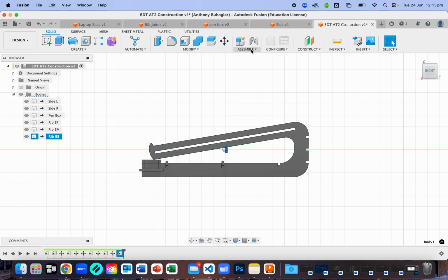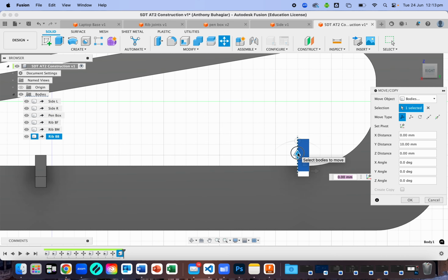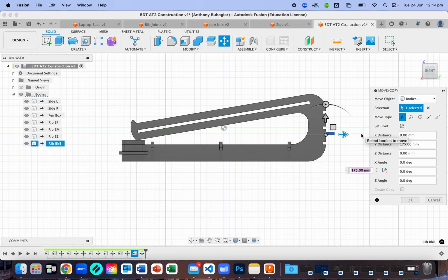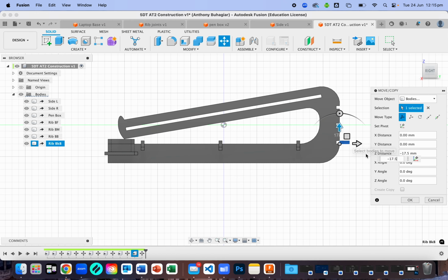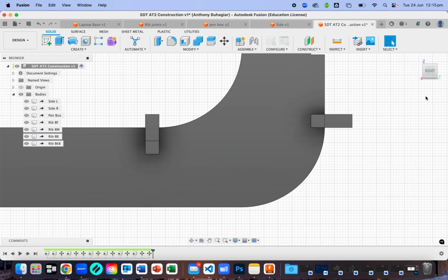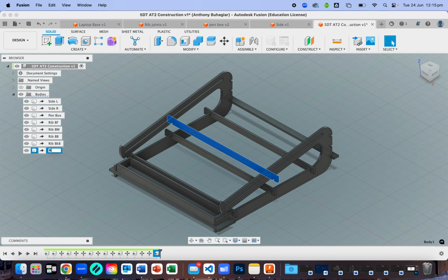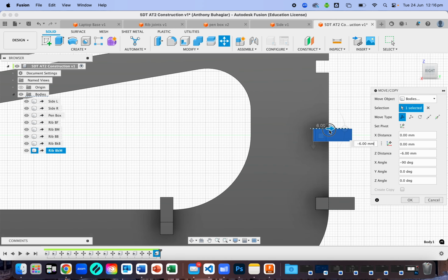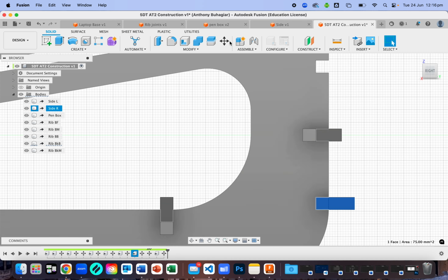And then I'll have a slightly different notation system for the ribs on the back piece, like rib back bottom, rib back mid, rib back top. So just have some kind of notation that you understand, so that if you need to adjust or move a particular element later on, you'll know what element you're selecting.